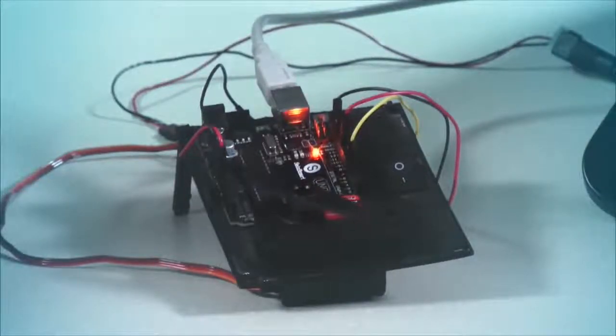Now, why is it still moving a little bit? It's turning just a little bit. That 1500 value, right? These continuous rotation servos come with a little adjustment to the potentiometer in them that you can zero. So you can physically zero out that 0 point, so it would be where it is supposed to be. This one doesn't have it quite right. So we could adjust that 1500 to get it to stop, or we could physically adjust the servo, which is probably the best way to do it.